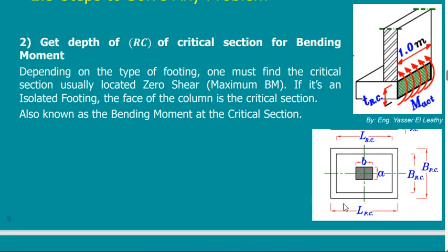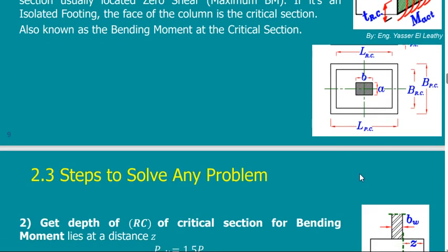Of course, design of isolated shallow foundations is very straightforward and simple. We said before that the main issue is to know: do we have a working plain concrete pad, or is it just added as an extra precaution to ensure that you are working in a clean environment, putting your steel and concrete without any contamination with the soil?